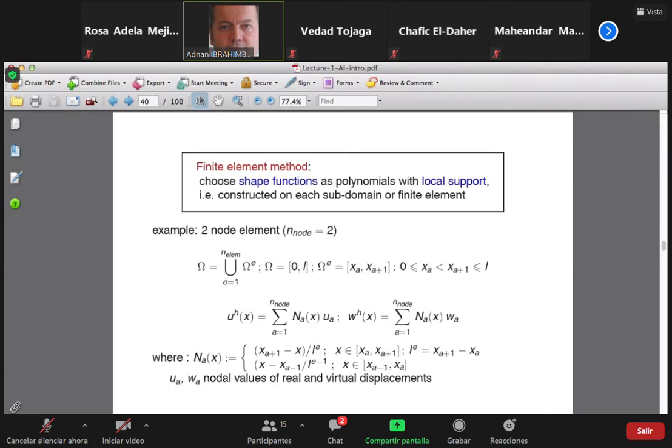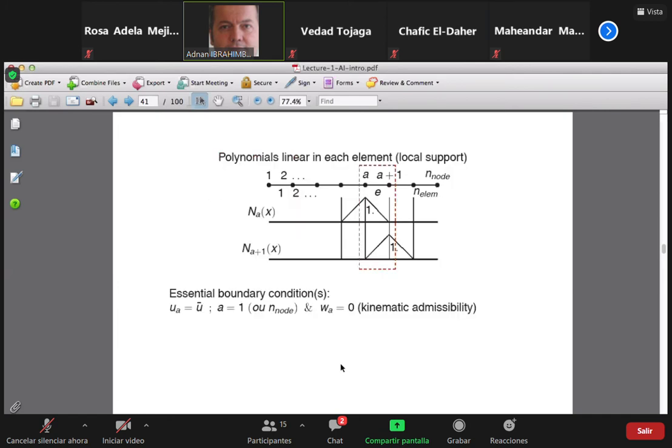So for this particular case, you can be sure that this u_A is nothing else but the nodal value of the displacement field, and it gives you a physical interpretation of the computed result, which is certainly much more meaningful when you're trying to obtain some kind of a good result. So this is really the easiest type of approximation I can imagine, that is based on top of the two-node truss bar element, where you actually have a global point of view in constructing your structure.